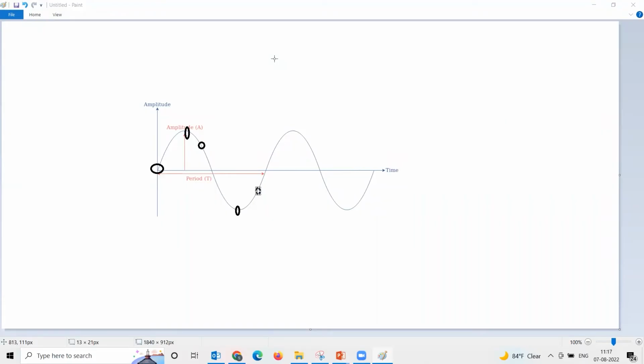Let me repeat. Your short circuit current in real time will never ever match the short circuit current in ETAP. Why? When you are performing a short circuit in ETAP, you have assumed that the fault is a bolted fault. You have assumed that there is no network change during the fault duration. You have assumed that the C factor is 1.1. You have assumed that there is no change in type of fault from the start of the fault to the end of the fault, etc. These are not really the assumptions of ETAP, they are the assumptions of IEC 60909.